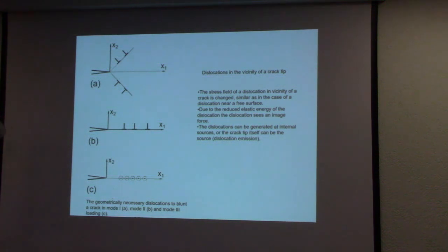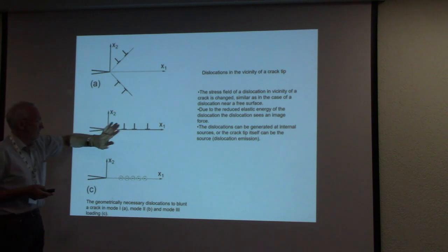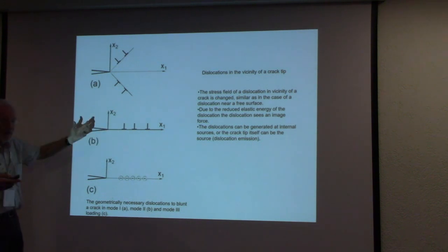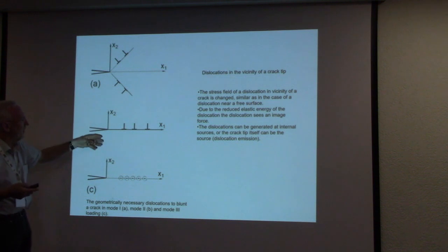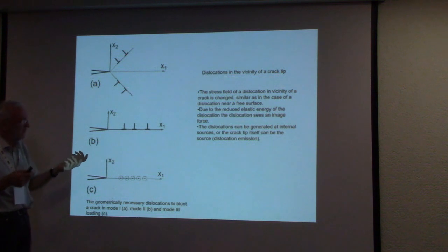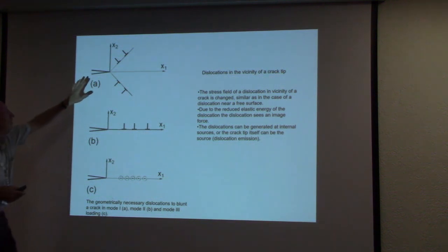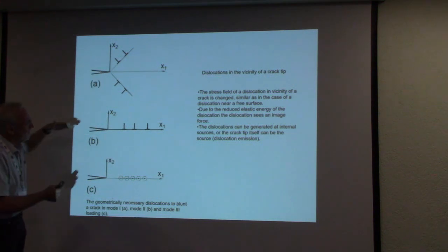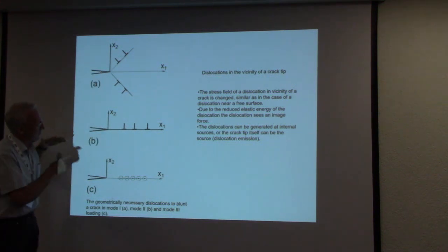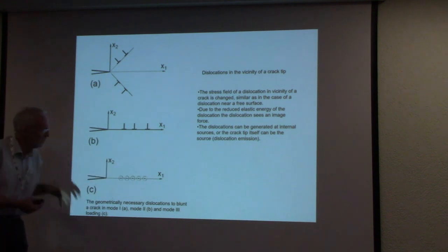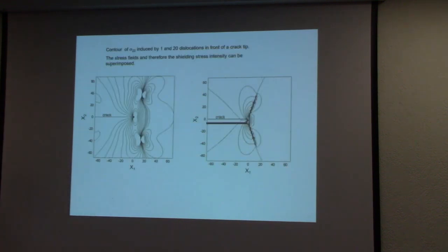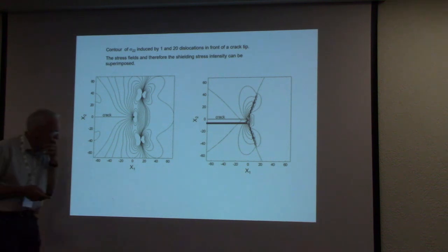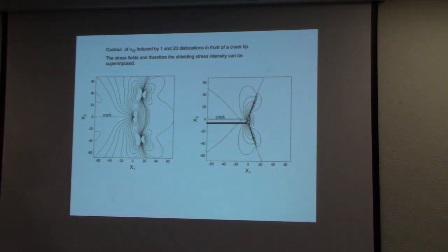Okay? So, for this consideration of the stresses, the dislocation mechanics point of view is the simplest one, because it is really analytical. You can analytically describe the stresses at a distance of nanometers. When you realize plasticity, for example, in mode 1, mode 2 loading, this means that you have edge dislocations, and screw dislocations to realize a mode 3 deformation.